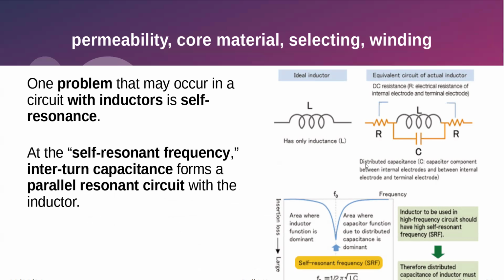Issues with inductors, similar with capacitors, is self-resonance. So you have turns, so the wire is close together. You have effectively capacitance between the windings called interturn capacitance.